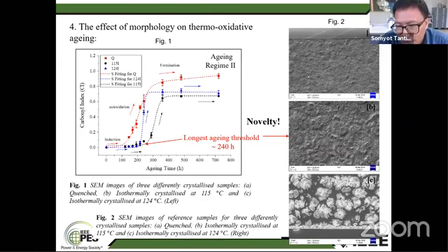But in figure B, the crystallization process is much slower. We crystallize the polyethylene at 115 degrees Celsius for 1 hour. So you can see the white lines here in the figures. This is a lamellar structure, or the crystal structure of the polyethylene chain, that's filling the space throughout the bulk of insulation.